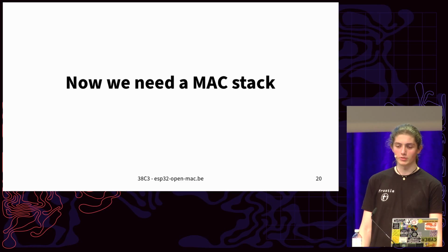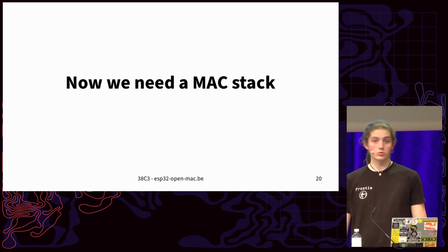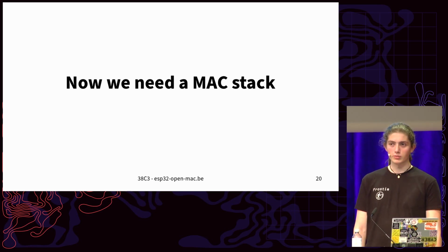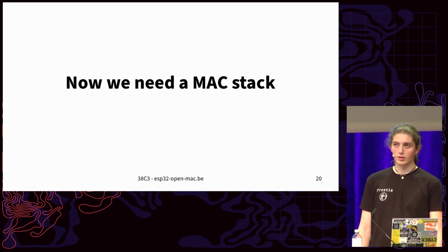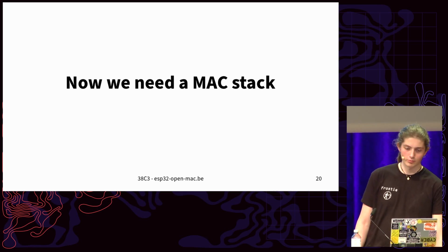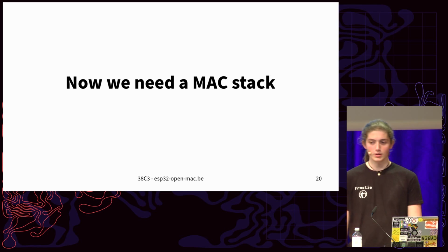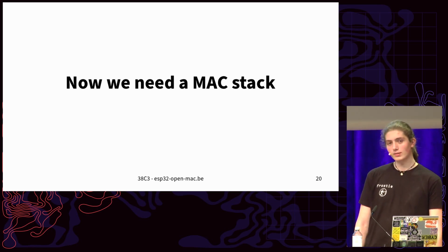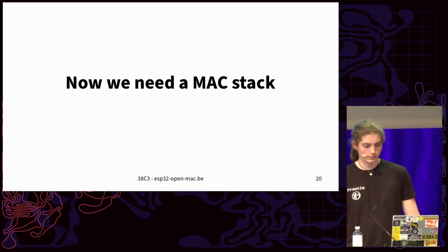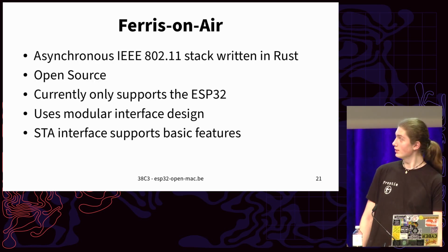And the stack on Espressif chips is adapted from FreeBSD. So we could go and use the one from FreeBSD or the one from the Linux kernel, mac80211. But those would be hard to port and are more geared towards host environments with a bit more resources than 520 kilobytes of RAM. But writing our own MAC stack would be a ton of work. So that's what we did.